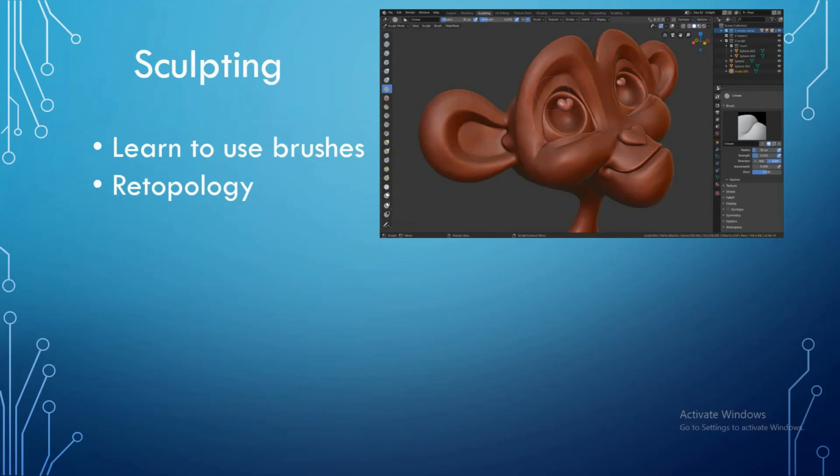Sculpting, again, is another important part of modeling. It is not essential in every project, but if you want to make especially organic looking meshes, you need sculpting. So you'll learn to use the variety of brushes that exist in Blender and also how to do retopology, which involves creating a less detailed version of your object, especially if you want to bring it into a game that you're making in something like Unity or Unreal Engine.